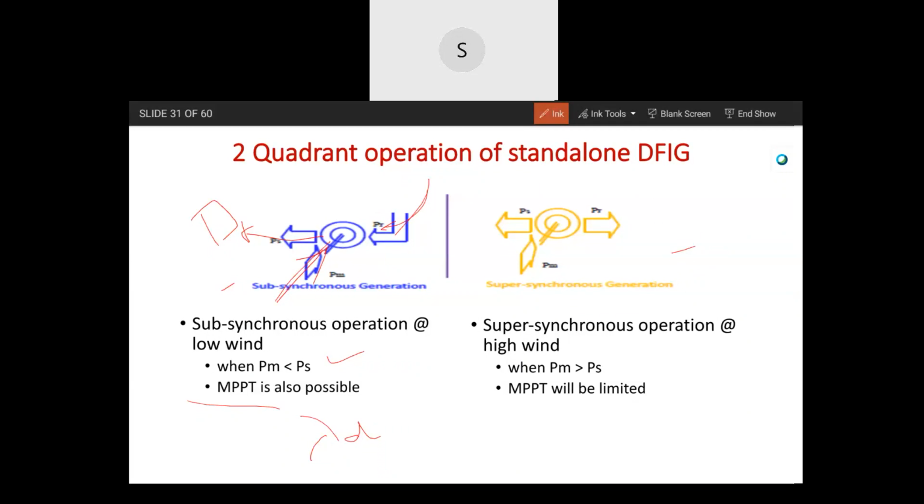Depending on the load impedance, the operating point will vary. That is, the power output of a solar panel varies even when the irradiance is kept constant, depending on the load impedance. You cannot change that load impedance, so there is a converter in between, and by adjusting its duty ratio and the voltage to the load, you can keep the panel operating at its maximum power point.